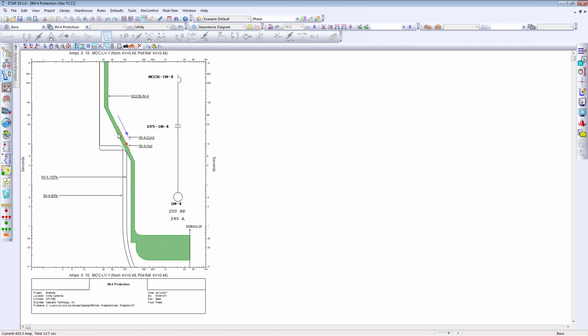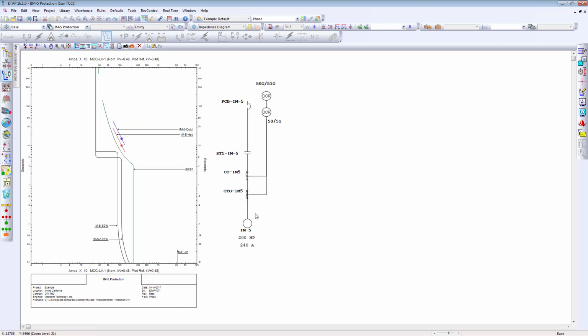Then a single breaker with the solid state trip unit for protection of both operating and thermal limit curves of the motor as one. This is a relay applied to the low voltage motor. It is sending the trip signal to the low voltage breaker, possibly a power circuit breaker. Again, overload protection and the short circuit protection.